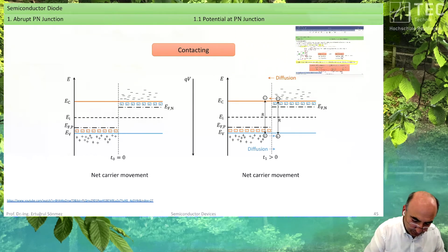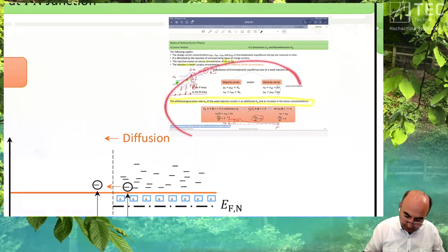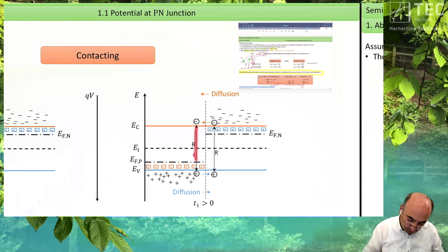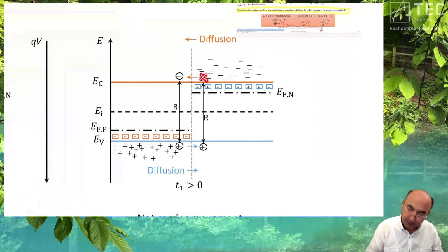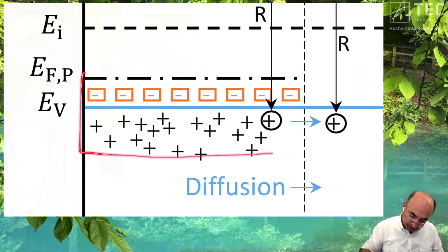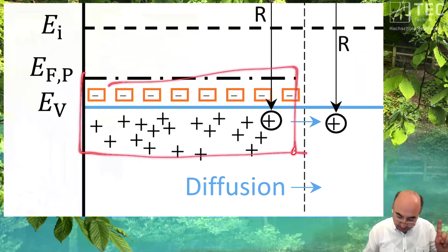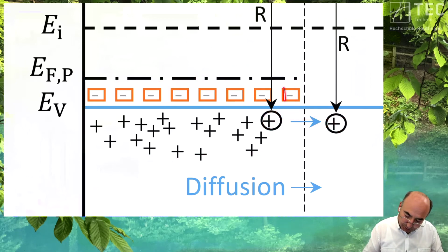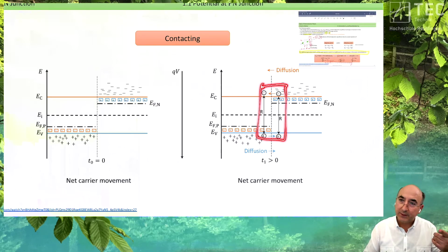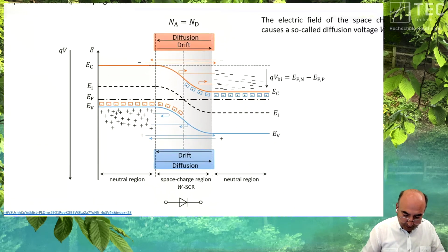Okay, so remember please, this slide we have learned to this recombination. Okay, so diffusion, recombination, diffusion, recombination. And each electron which disappears here and each hole which disappears here leaves back one not movable partner. So at the beginning, this area is neutral. But if one hole diffuses away and is destroyed, recombined with an electron, you leave back the charge in the space. And each process of this diffusion recombination makes this happen.